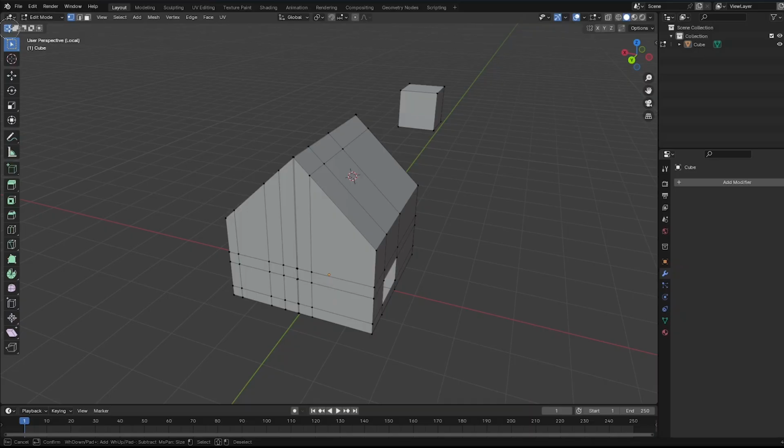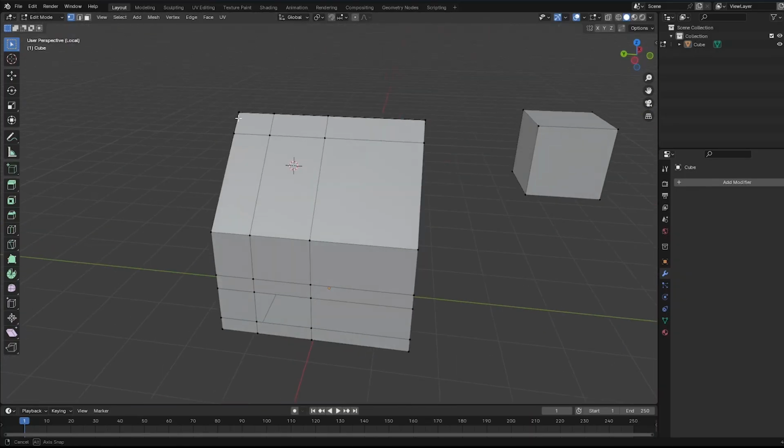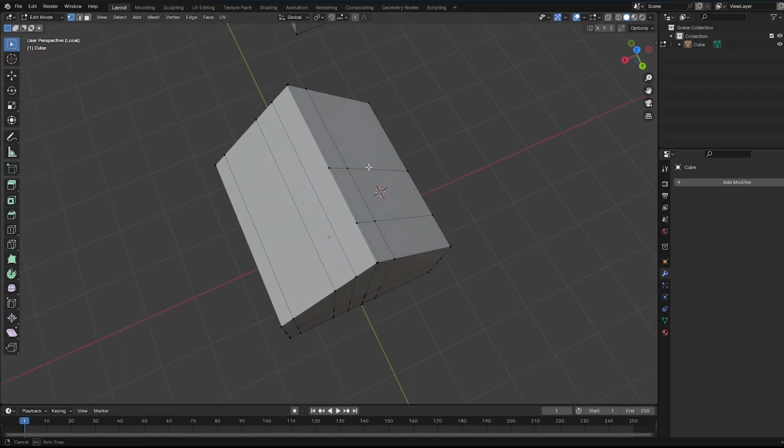Or you can just press T to move it up and down. So this basically turns into a circle selector. You can also zoom in and out if you want to, but it's basically up to you however you want to work with it. And you can also move back to your tool over here. You can apply this selection tool back again, and you can also increase it up and down. And when you press C back again, it will turn into that selector.